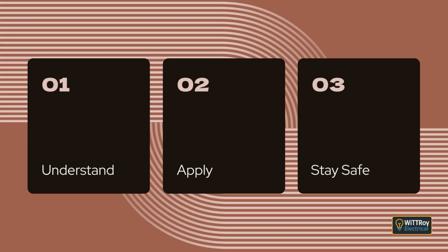Clause 3.9.4.3 Wiring systems under wall lining or roofing material. Clause 3.9.4.3.1 Prohibited locations. Wiring must not be installed in the space between roofing material and its immediate supporting members, or in similar spaces behind wall linings where a person may reasonably drive a nail or screw. These locations include the space between battens and roofing tiles, or between corrugated roofing sheets and their supporting members.